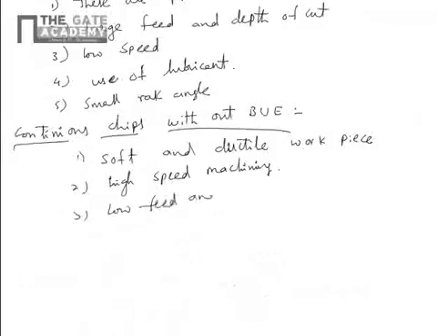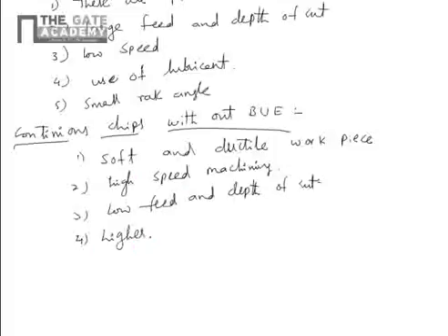Low feed and depth of cut. As the forces decrease, heat generated also decreases. Chances of adhering the microchips is less. Higher rake angle. Use of lubricant.